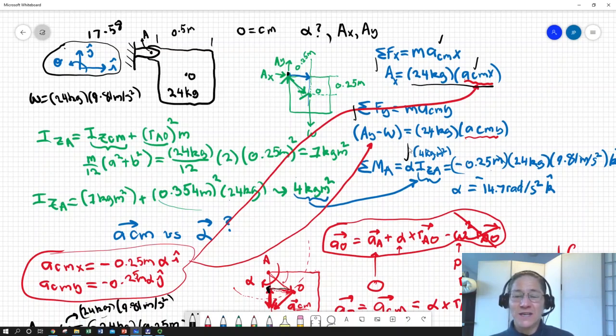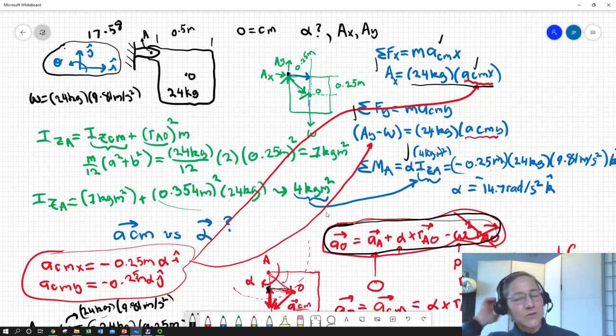What we did is use our multi-directional kinematics relationship: the velocity and acceleration relationship for 2 points on a rigid body. 2 points always contain 2 equations. So it's this red, good old 2 points on a rigid body acceleration expression that gave us our additional 2 equations. So we back-inferred force from acceleration in this case, which is definitely something you'd never do in statics.